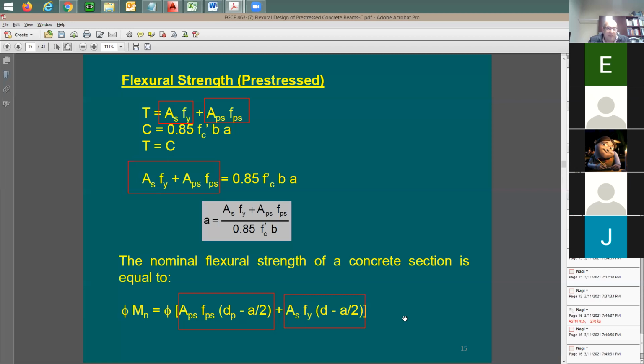And usually it's going to be up to you to decide if you really want to add some additional conventional rebars with the prestress strands. It's going to be a design thing. Sometimes you use number 7, another person is going to use number 8, right? So someone would like everything to be only prestressed. Someone else is going to say, why don't we add some conventional rebars? Because this is going to be, let's say, post-tension.